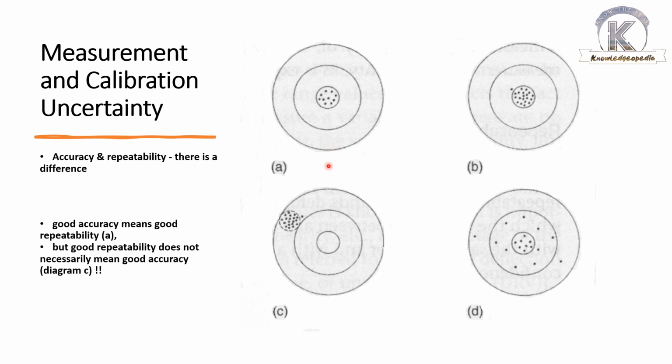That flow meter should have good repeatability. That means 170 ml at least it has to reach every time. It should not be that on one occasion it gives the correct 200 ml, the second time it overflows and gives 230 ml, the third time it gives 170 ml. This type of behavior is not accepted.